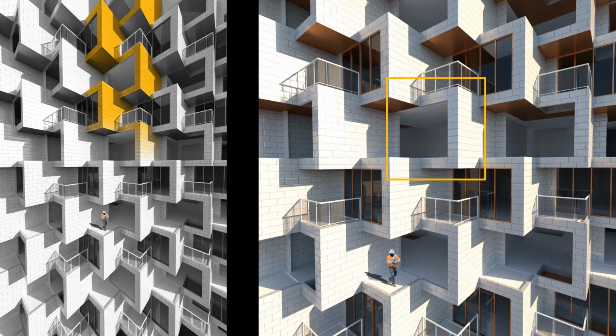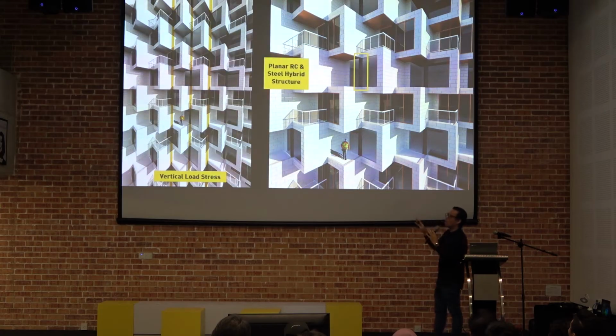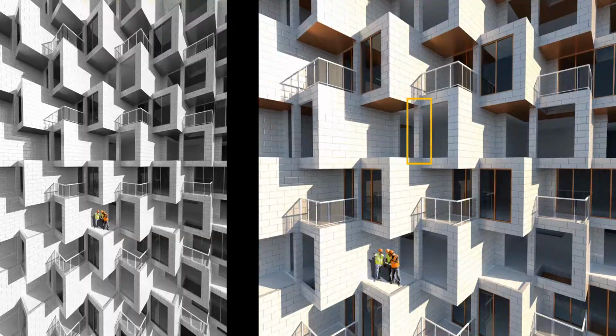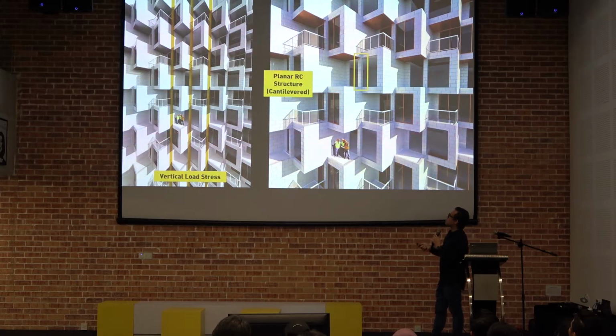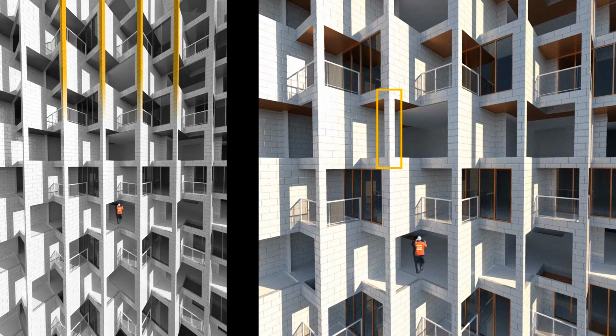Okay, the facade, which is one of the important parts. One way to do it is to use volumetric structural components, and it will look like this. Of course, knowing the question that will come after that, we made a more economical version where we include a composite panel with a steel structure, so that we can have the load go directly down. The idea was to make sure that the steel structure blends together with the rest of the window wall frame. This is the more economical version. Obviously, this is an RC flat panel with two fenestrations, and we try to address the load on the cantilevered part. These are versions which they can scale up or scale down.